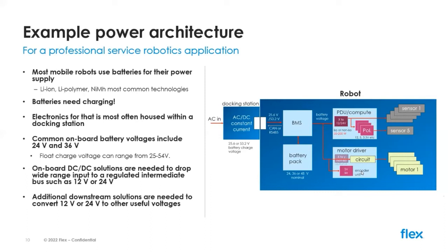So again, there will be a need for point of load converters to do that conversion stage. They are often either discrete solutions or, more and more as the complexity of the robot gets greater, the more compute power is needed, the more current is needed from the point of load converter. And so the modularity of solutions such as those from Flex Power Modules comes into play.